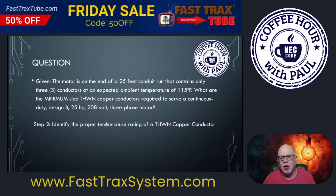Now, you're probably all familiar with the wire that you buy. It'll be THHN/THWN-2. Well, that -2 signifies that it is also 90-degree rated insulation, which is important when we're doing an ambient correction later. But in our case, it's only THWN.